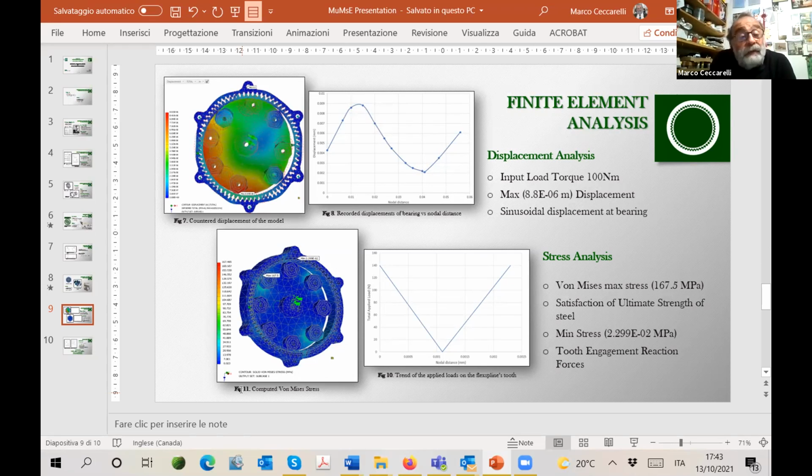That is quite curious, seeing the main stress in the wave generator. Well, it can be reasonable, because if you look at the concept of the design, we may expect that the most critical part is the flexible spline. And in fact, most of the attention in the design is addressed to the flexible spline.